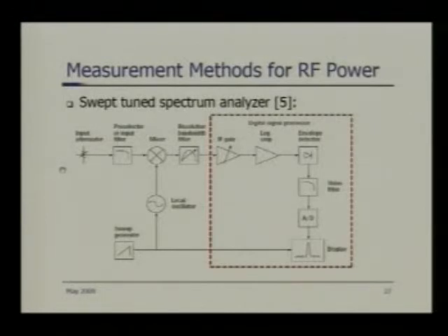So if the input dynamic range says it's 10 dBm, the maximum power that can go into the front end of the instrument is 10 dBm, right? But when you are programming the spectrum analyzer measurement at 10 dBm, what you lose is resolution. There are trade-offs, but let's just concentrate on the basic mechanism used in a spectrum analyzer, which uses a swept-tuned mechanism to capture the RF spectrum. So there is an input attenuator to accommodate the input dynamic range.